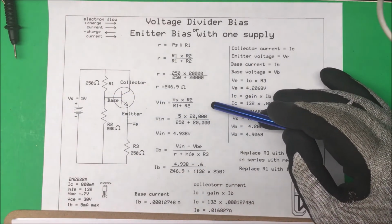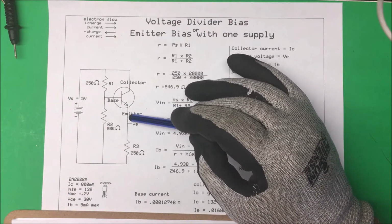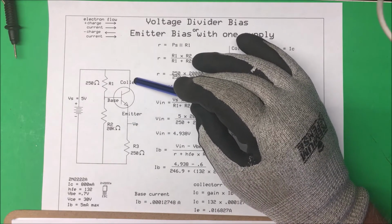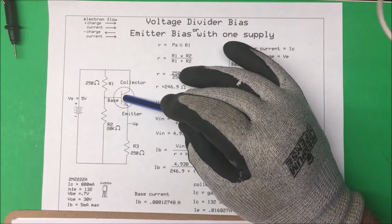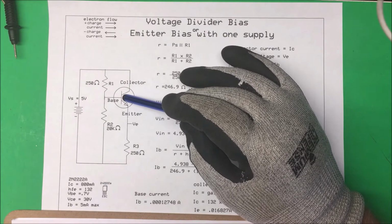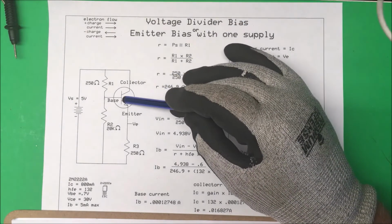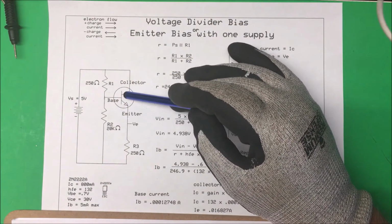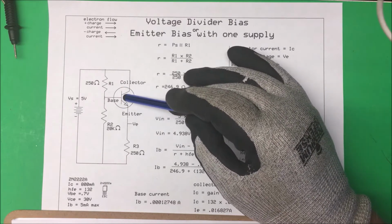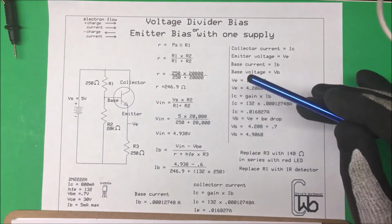Okay, so the emitter is, in this case, N material and it's heavily doped. It's got a lot of electrons in it, and the collector is moderately doped with extra electrons. But the base is a thin layer and it's P material, and it just has holes in it, but it's lightly doped, which just has very few holes in there. It creates two depletion regions on these PN junctions in the base there, with the electrons facing in and the positive charges facing the N material.